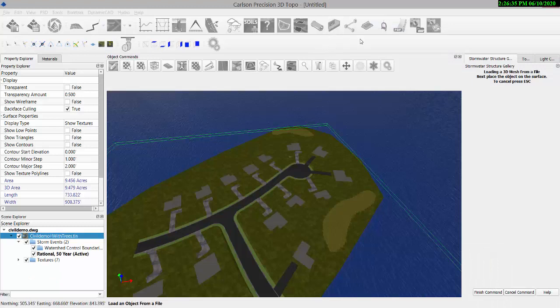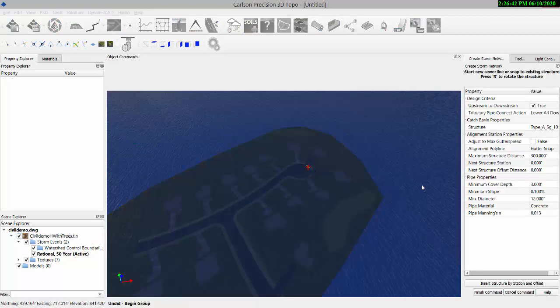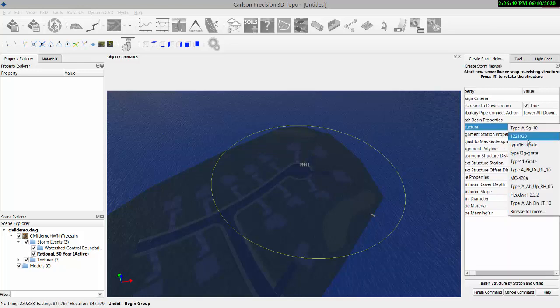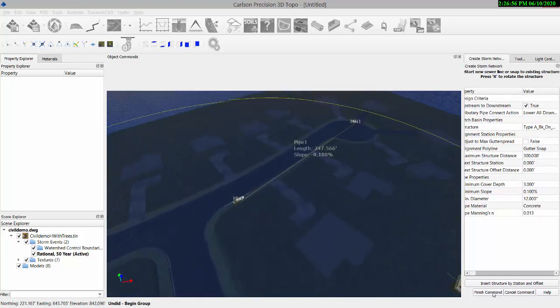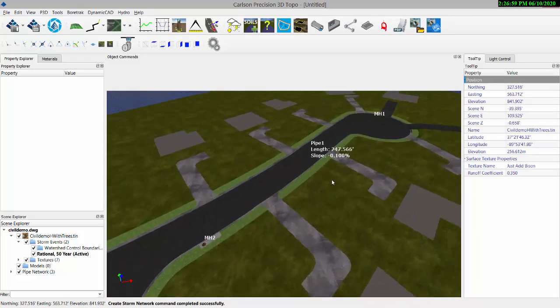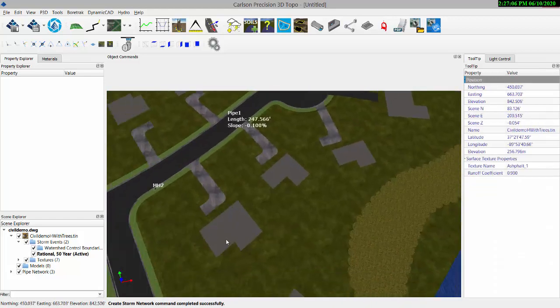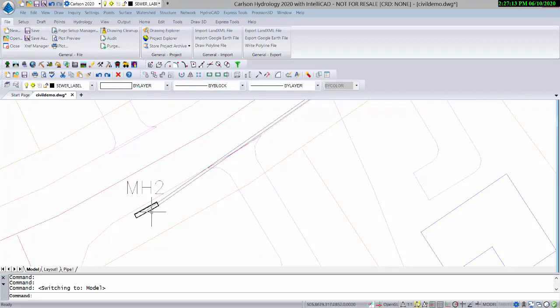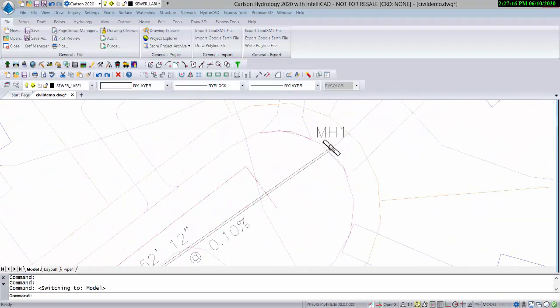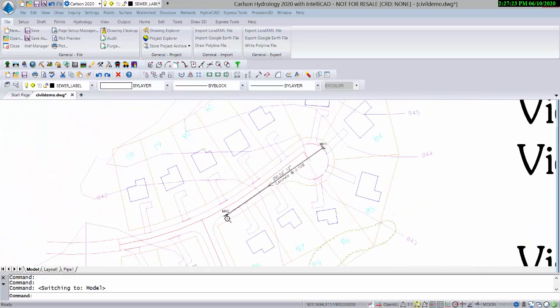We'll show you. So if I go in here, and let's cancel what we were in and put a couple in here. Let's put in this 10-foot inlet, and the next one will be the right 10-foot with the manhole facing downstream. And we're going to finish the command, and you can see we have two inlets in. This one has the lid in the middle, and as we go back to the CAD into the model space, we have the mapped symbol, which is exactly 10 foot. It's set to a fixed size, not a unit size in this case.